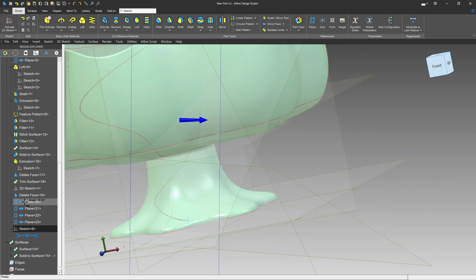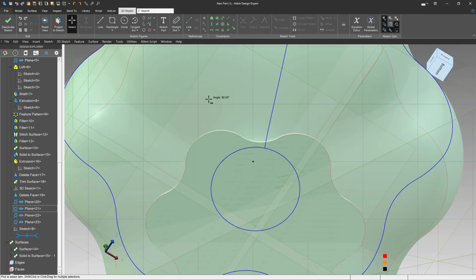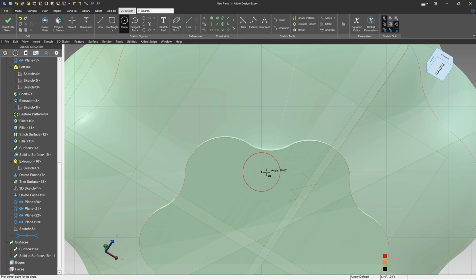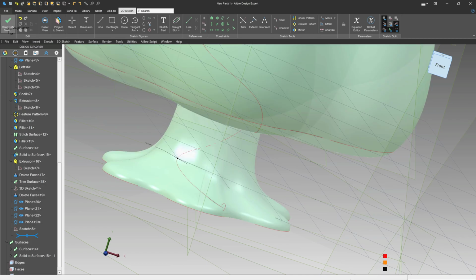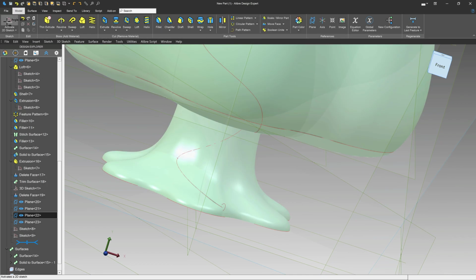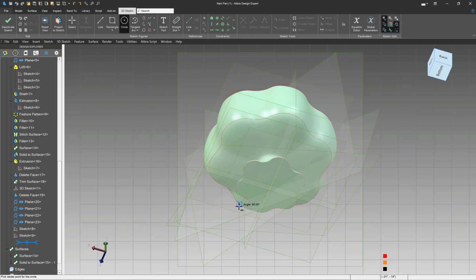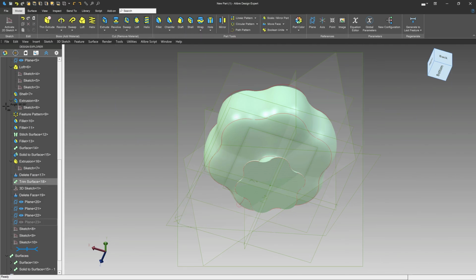And then we want to go small on our next plane. So I'm going to not edit, but rather create a sketch on my next plane. And we'll say maybe 0.025, right? It'll go really small. And we can adjust that later if that turns out to be too small. And then we'll go on the third plane that we made and create a sketch on that. Maybe we want that to be relatively big. Maybe we'll say 0.3, right? Something big. And then I'll go on my final plane that I created, activate a sketch on it.